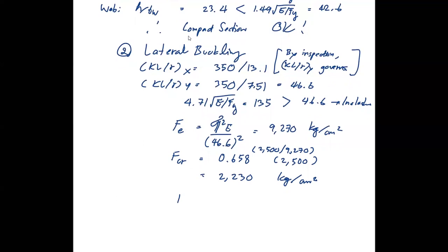And the nominal strength here is 120, that's the area, multiplied by this, divided by 1,000. So 268, just rounding off a little bit with my table. So now you know P nominal here. In the end, you should also make the summary somewhere to write nicely.